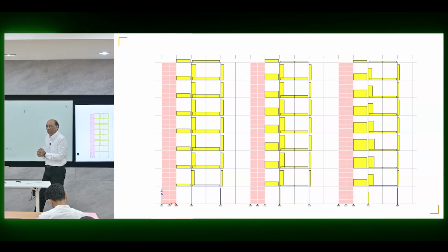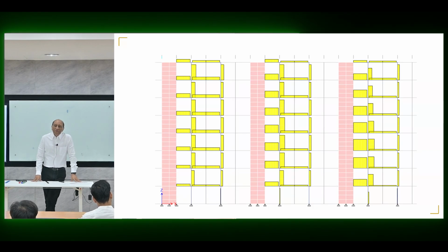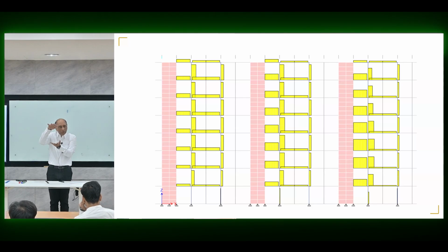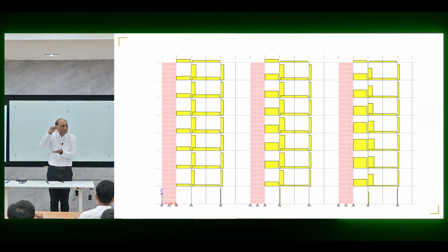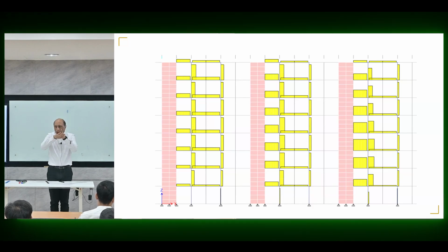Okay. So the solution to the problem is very, very simple. I showed you cracking and everything. I gave you so many openings, but nobody picked it up. So the solution is that whatever capacity of the shear you have, you first of all utilize maximum capacity, provide maximum reinforcement, provide diagonal reinforcement. Whatever you want to do, but there's a limit to that. Get that shear capacity with the maximum that you can, steel plate, whatever. They're not the solution. And then from there, calculate how much moment is needed to produce this shear and limit your flexural reinforcement to that level.